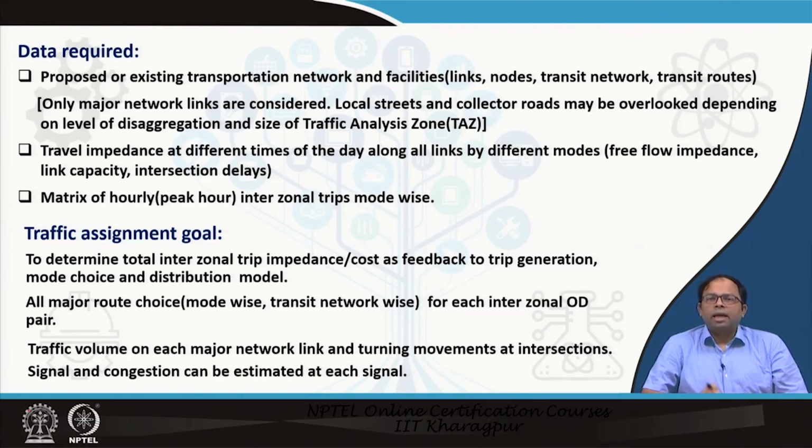So, this part is called dynamic traffic assignment, which will be also covered later on, but that means that at certain intervals people update their route choices as well. So, in that sense, we need to have a detailed understanding of traffic signals, just to ascertain what would be the total impedance and increase of impedance when the capacity increases, and that also influences the assignment part as well. Even if we don't change the route choice, it will change the link assignment part as well.